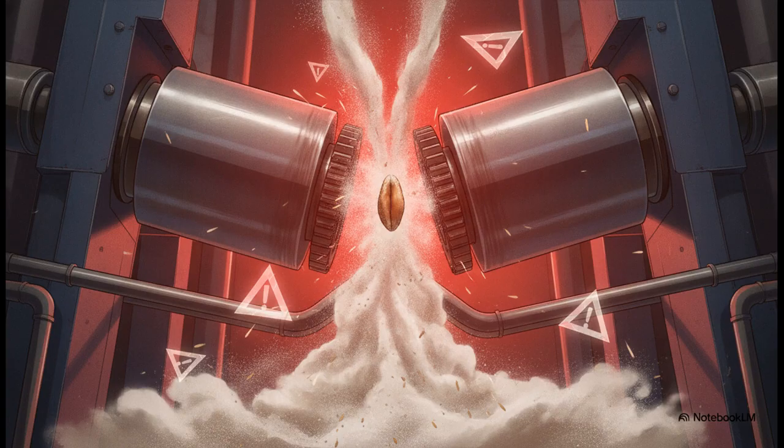It fundamentally alters the mechanical action of your primary machines. When that differential drops, the precise scraping vector degrades into a blunt crushing action. Your facility will inadvertently pulverize the outer bran layer into a microscopic powder, rather than maintaining it in large, manageable flakes. Once this unsiftable bran powder mixes into your fine flour stock, it is mechanically impossible to separate using standard plansifter technology. The immediate statistical consequence? A sudden, uncontrollable surge in final ash content, an immediate downgrade of your primary product, and a significant hit to your operational margin.